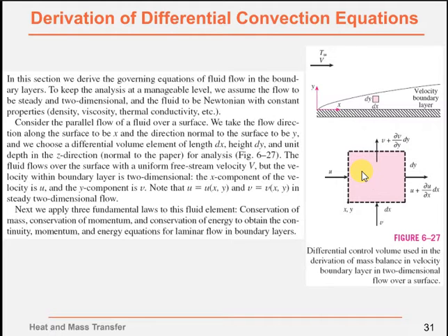Now we will apply three fundamental laws to this fluid element. We will apply conservation of mass, conservation of momentum, and conservation of energy to obtain the continuity, momentum, and energy balance equations for laminar flow in the boundary layer.